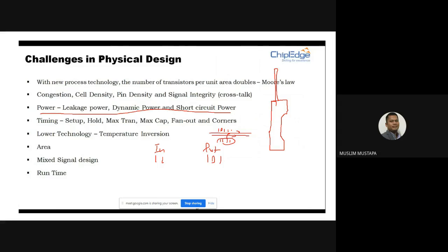That's what you get from the simulation. But after physical design, because the line is congested and because of the delay, when you insert 1 1, your output might be 1 1 1, for example. This means something is wrong with the timing inside the circuitry.